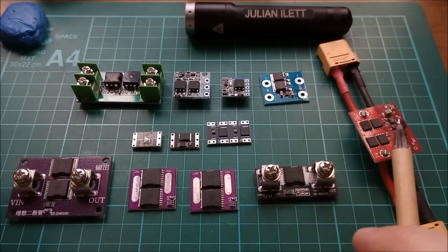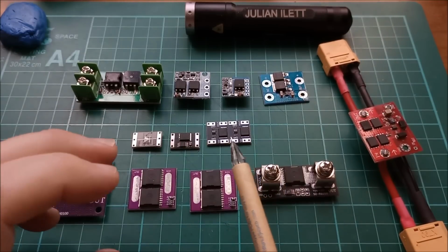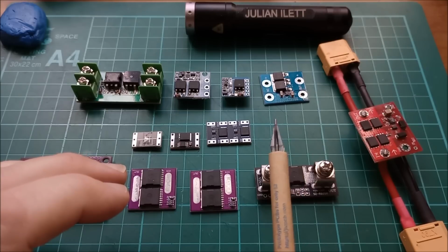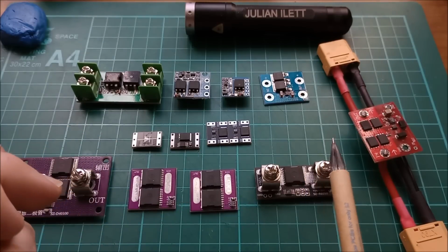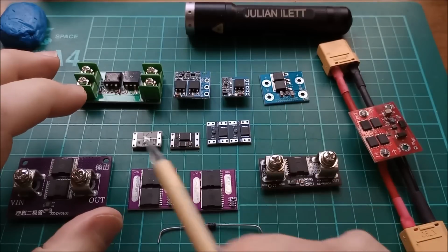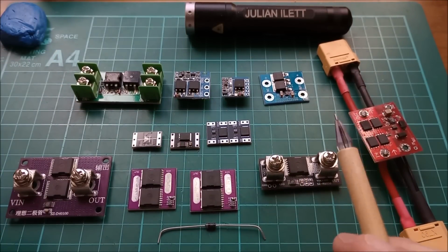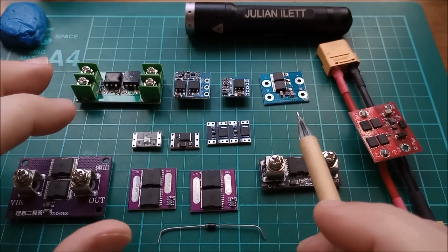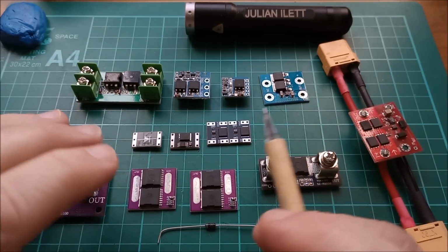So to help address the main problem with conventional diodes, which is this voltage drop between anode and cathode when there's a current flowing through it, we have these things. These are ideal diodes. Now, of course, these things don't solve all of the problems of conventional diodes, but they do address that voltage drop issue, which is one of the biggest problems because, of course, it generates heat and wastes power.